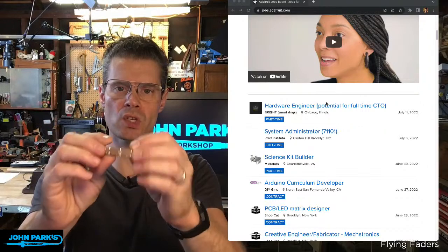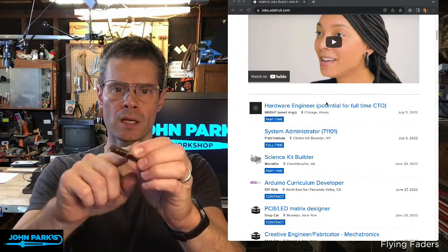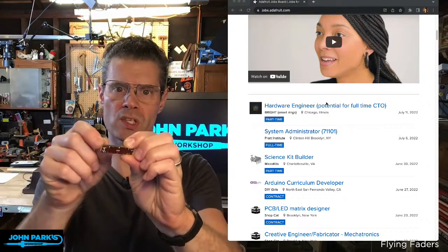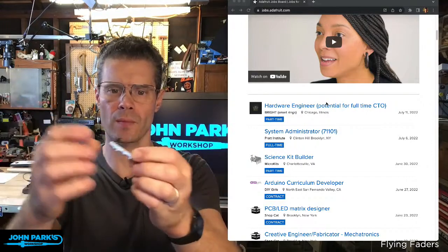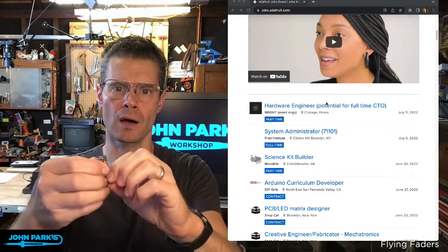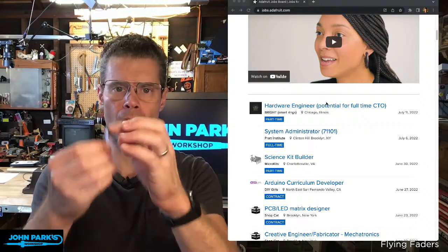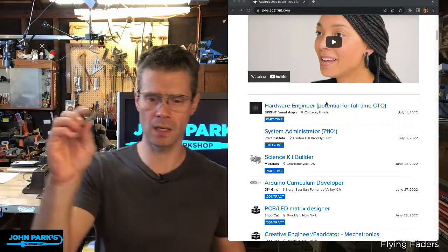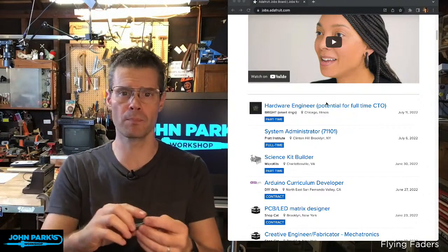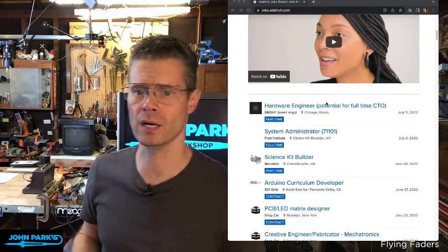So we can use an analog read to tell where this is, how much resistance we're getting, usually 0 to 10K, usually it's a 10K pot, pretty typical. That is sort of the big part 1 of what that product right there is.